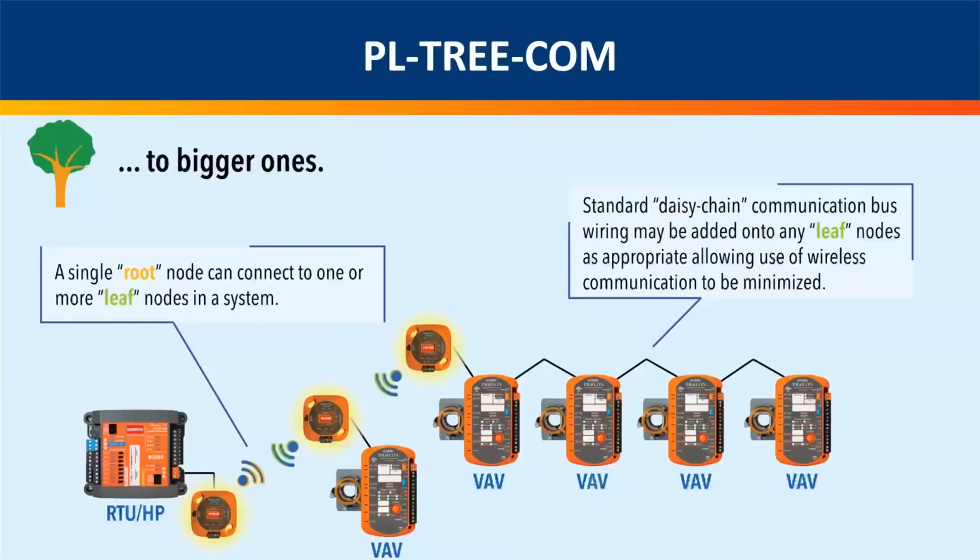So I have a question here. Is the root and the leaf the same device? Yes, it is the same device. What designates a root is turning on dip switch 8. Other than that, it's going to be your standard dip switch addressing that I've introduced you to using M2000s, using C1050s.